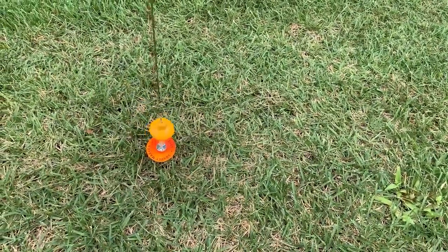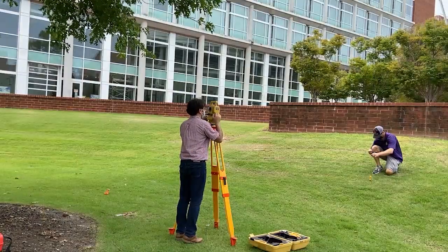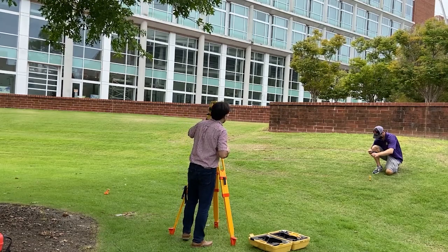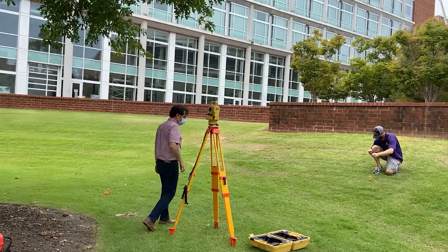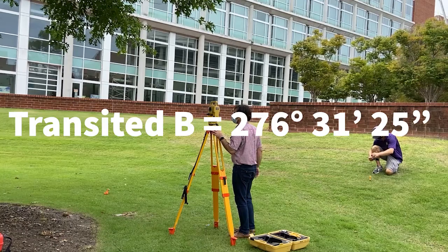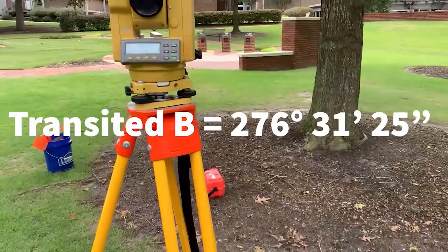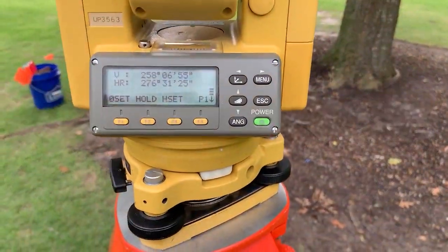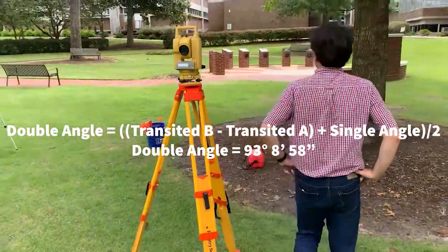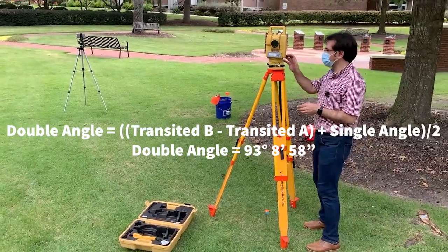I again shoot to the point, and then read that. This is 276 degrees, 31 minutes, 25 seconds. Then it would be my transited 2. Transited 2 minus transited 1 plus single angle, divided by 2, would be my double angle.